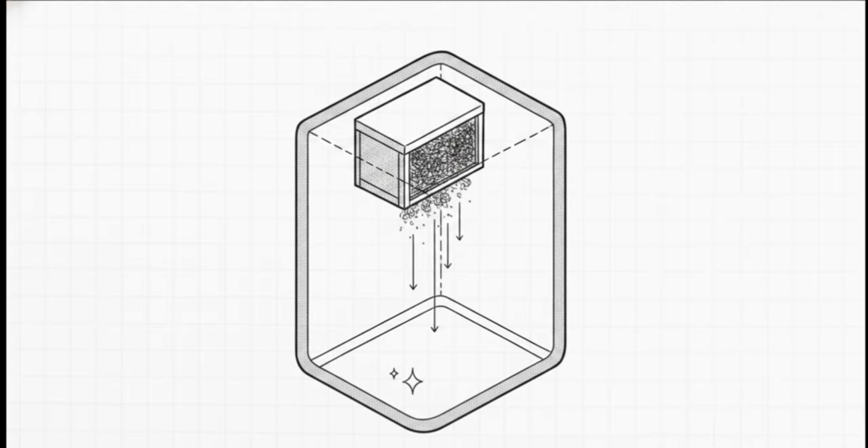Even false ceilings must be perfectly sealed so no contamination from the utility void space above drops down into the sterile area. And pumping air into this room? H14 HEPA filters. These boast a 99.995% efficiency rate at catching particles as tiny as 0.3 microns. Every single dry architectural feature we're looking at directly mitigates the cGMP risks we talked about earlier.